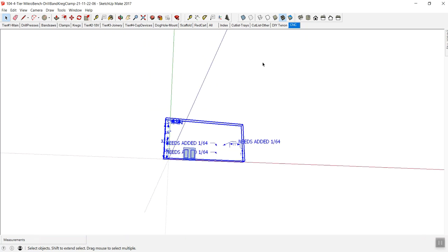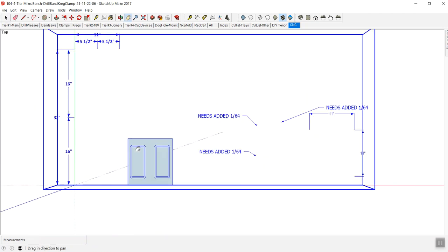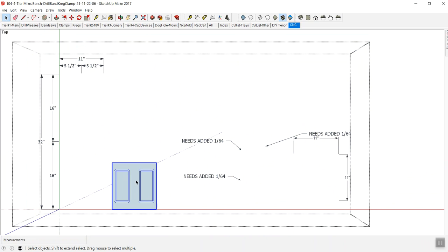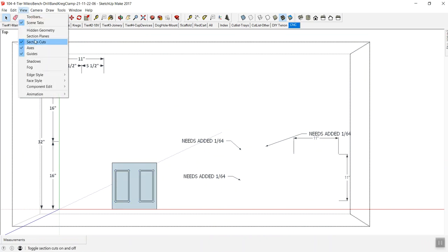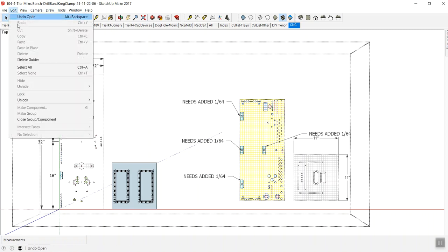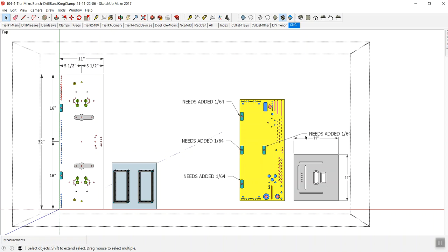all over the place. But if I go to CNC, it automatically tells it to go ahead and hide all that other stuff outside of this little rectangle. Now I'm in the rectangle, or in the group, so now that I'm in the group, I'm going to do a view. You can see there's some stuff hidden in here. I clicked on view hidden, so I'm going to do edit, unhide all, and as long as I'm in that group, it's only going to unhide the items within that group. It's not going to unhide all the other stuff that's out and about.